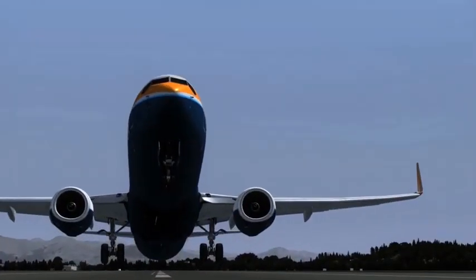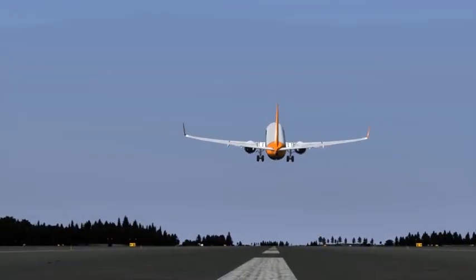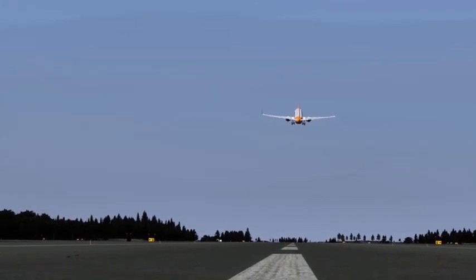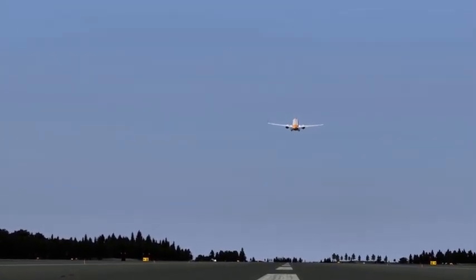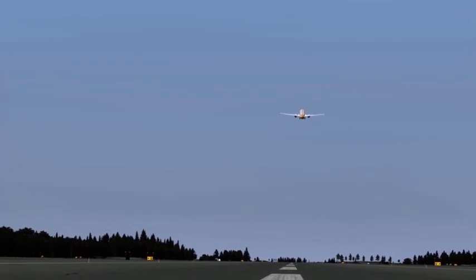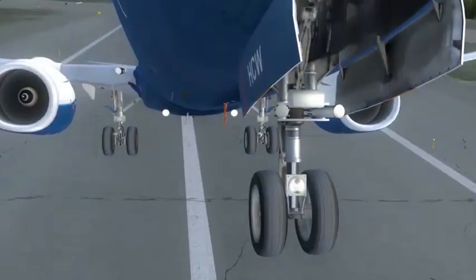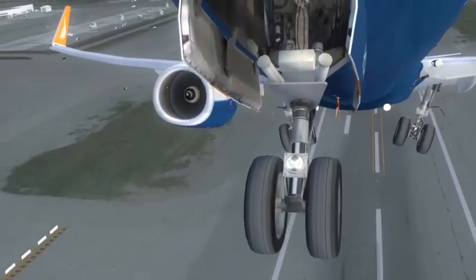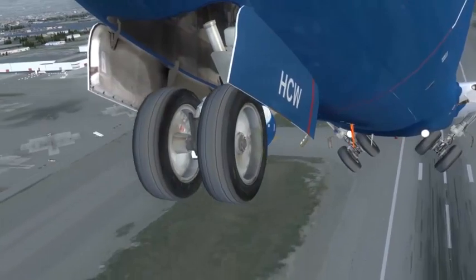Engine parameters are extensively discussed in the 737 NG engines lesson. To start the takeoff phase, the pressurization system must recognize the following conditions. N1 on both engines must increase past 60% for 1.5 seconds or more. N2 on both engines must increase past 89% for 1.5 seconds or more.